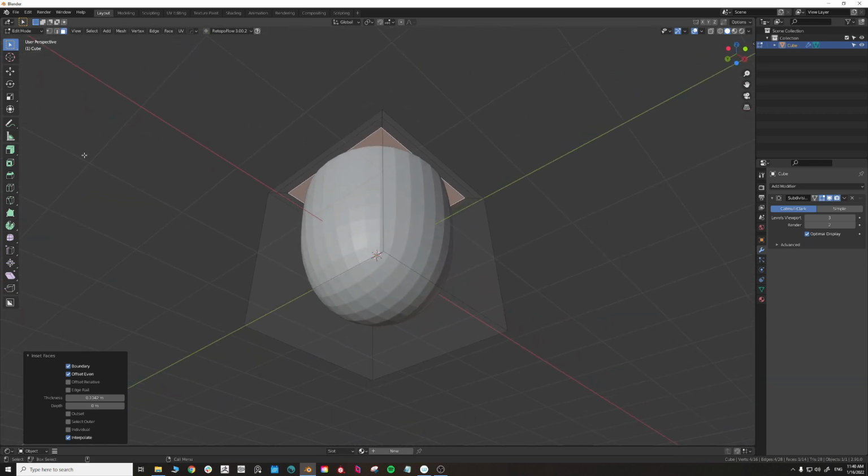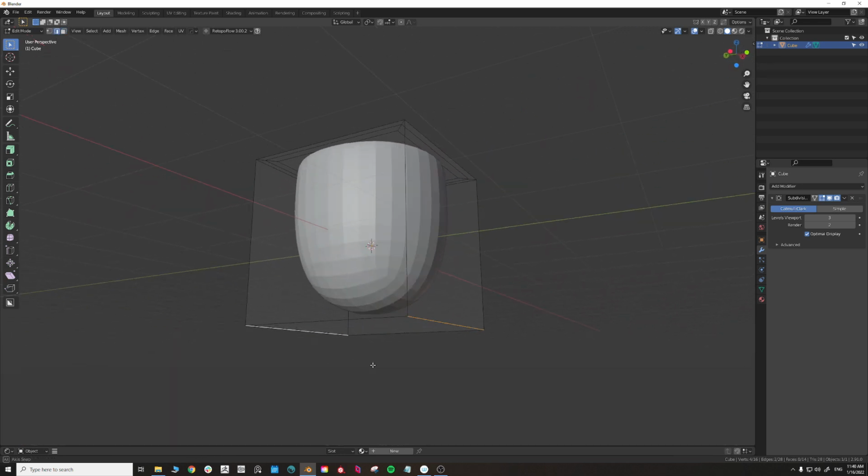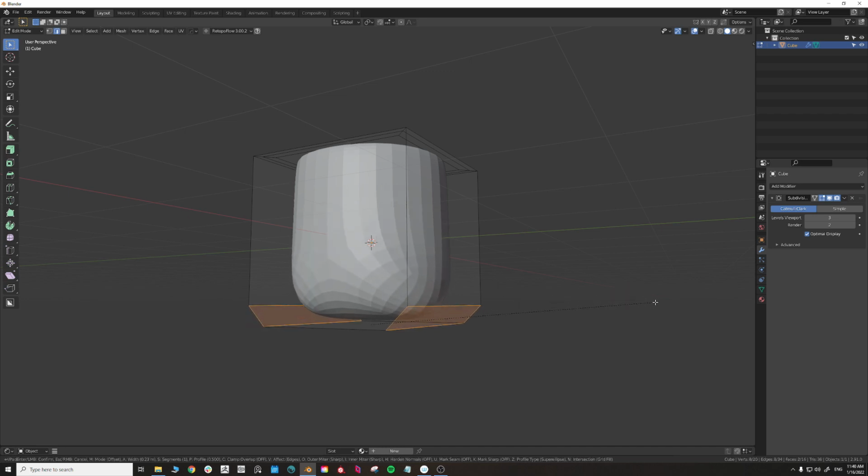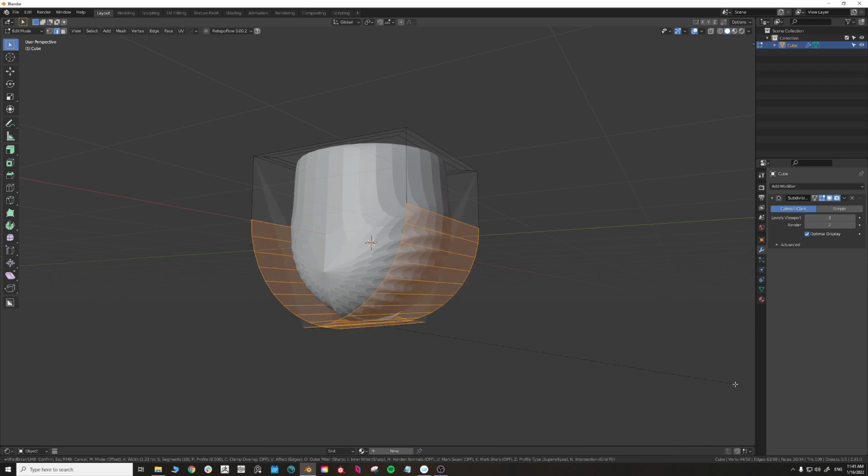Let's look at another option here. Let's go to edges, and let's take these two edges and bevel them. Control B, or bevel from right here. I'm going to use Control B. And if you look at how this form is getting distorted, you can see that it also works on the surface. The closer we have it, the tighter the surface is. But let's, for example, scroll with the mouse to add more geometry. You can see how this thing starts to change and create something really interesting in terms of just an effect. Let's keep it low.